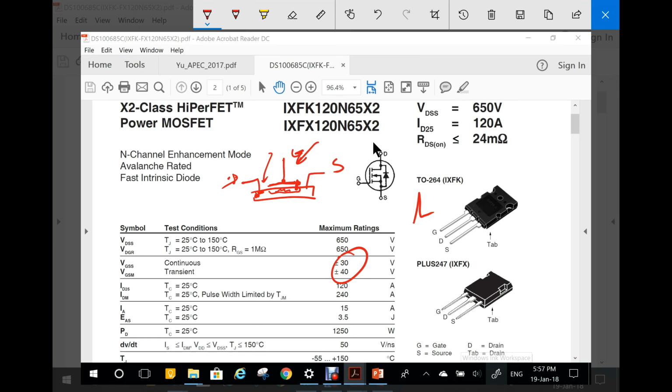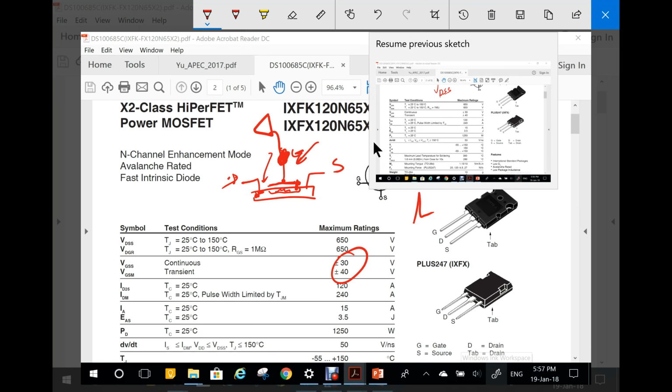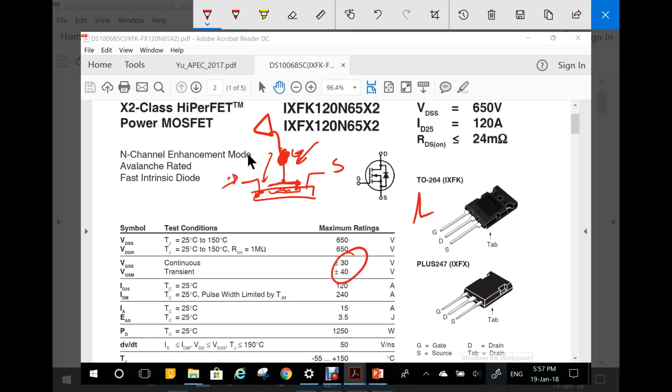So this is something to worry about, and you have to be very careful that the impedance of this point in the circuit, when you connect, say, a driver or any other circuit, will be low, so that this point will be kept at a controlled voltage and not be affected by some connections, by some source here that will, by say capacitive coupling, inject some noise in here. Okay, so we got this one, so let's go to here.